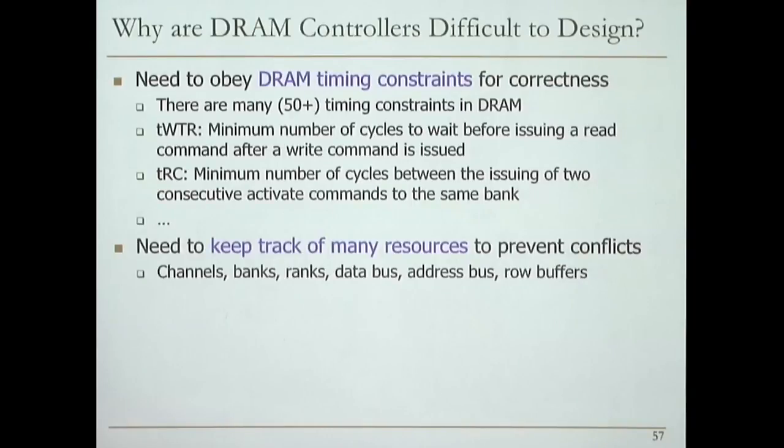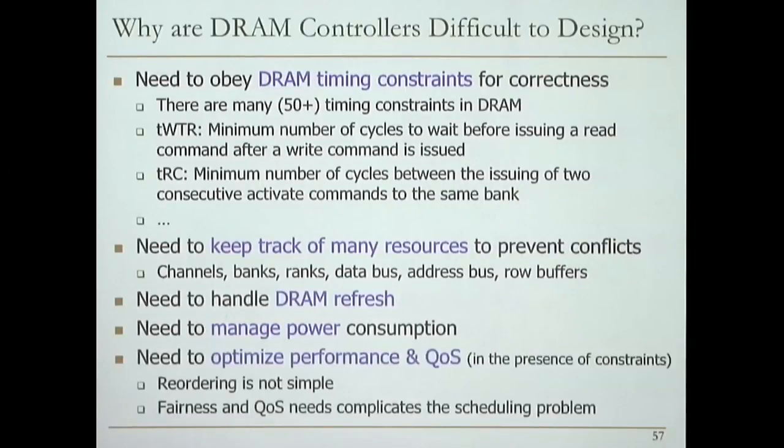On top of that, you need to keep track of many resources to prevent conflicts, and also to keep track of the timing constraints: channels, banks, ranks, data bus, address bus, row buffers. You need to handle DRAM refresh. You need to manage power consumption. You need to optimize performance. All of these affect your performance, depending on how well you handle those timing constraints.